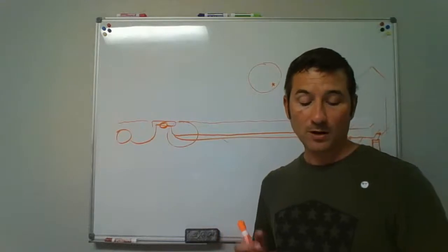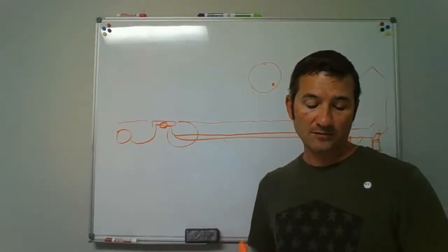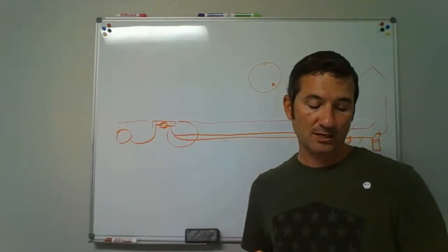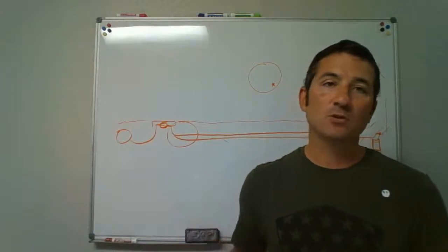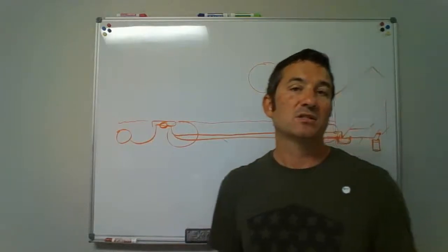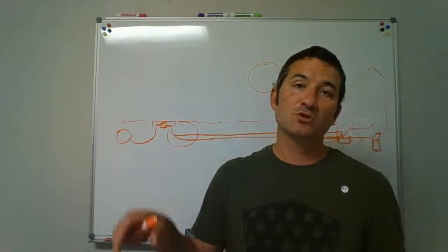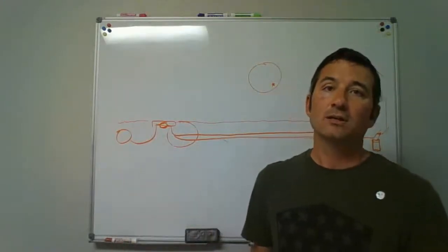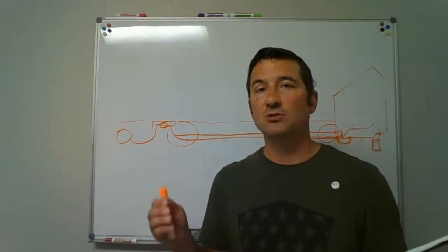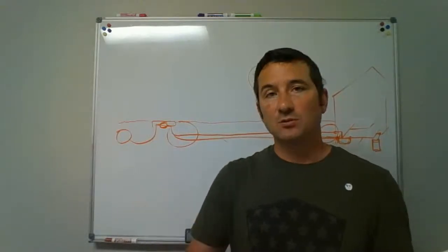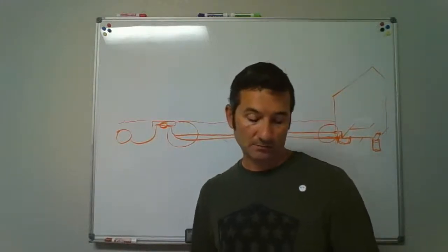Individual water supply, where a potable public water supply is not available, individual sources of potable water shall be utilized. So if the county or the city hasn't run water down there, it just says you've got to get another source of it. So you might have to get your own source of water by digging a well. Now it's going to be your responsibility, if you've got your own private source of water, to do periodic testing of that water just to make sure it stays safe for drinking.